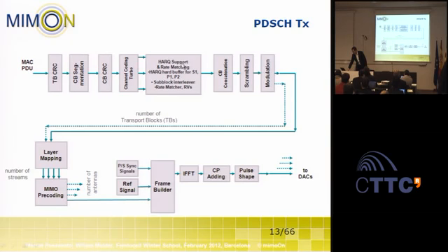So we are reducing the rate to 1/3, introducing redundancy, but this then enters the HARQ or rate matching buffer, which is a cyclic buffer, where interleaved versions of the systematic and the parity bits are written. Not all these bits are transmitted. Rate matching is performed, so only a portion of this total buffer is transmitted each time. And this of course depends on the channel conditions. If we have very good channel conditions at the user equipment, which is reported from the user equipment, then only a few bits are selected to be transmitted.